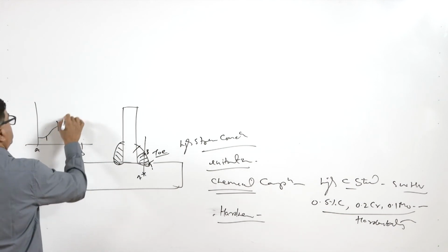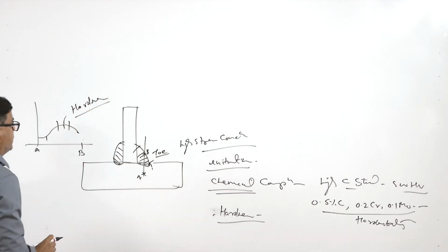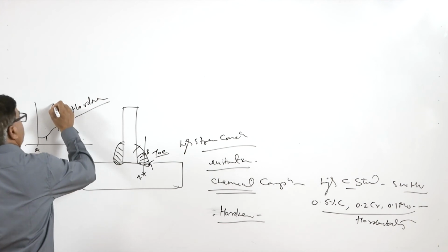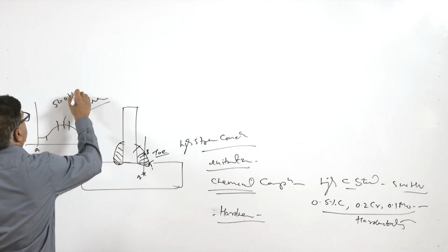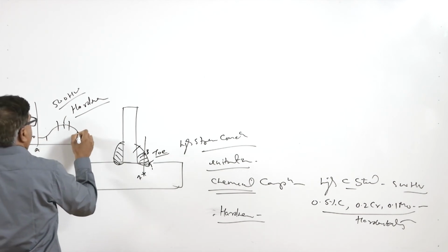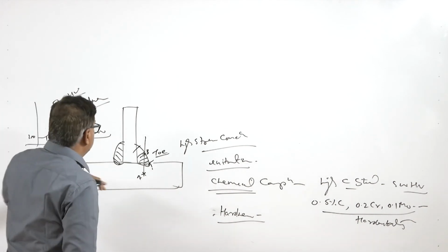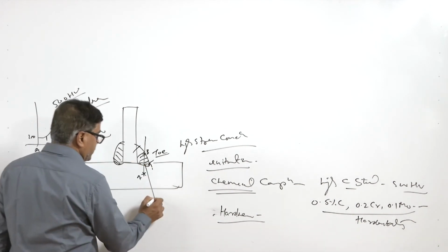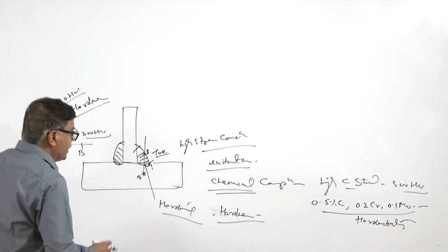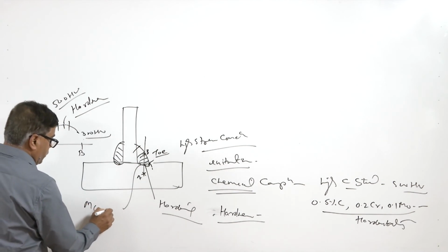So, the heat affected zone. The hardness of the heat affected zone is high in this case, say 500 HV, while the base metal is around 200 HV and the fillet is around 300 HV. This suggests that hardening of the heat affected zone has taken place. This is one aspect, and to find out why the hardening has taken place, we have to do the microscopy